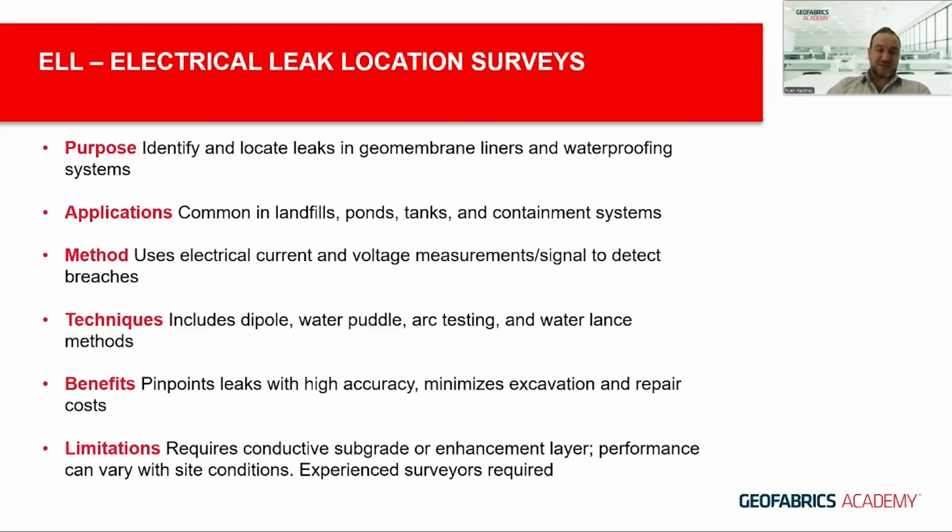And the benefits of conducting the survey are that it pinpoints leaks with high accuracy, and that leads to minimization of excavation down the line and repair costs when it's identified that there's a leak. There's also a benefit in terms of environmental protection as well. You're ensuring that the liquid that is being stored, which in some cases can be contaminated liquid, is retained and it's not polluting the surrounding environment.